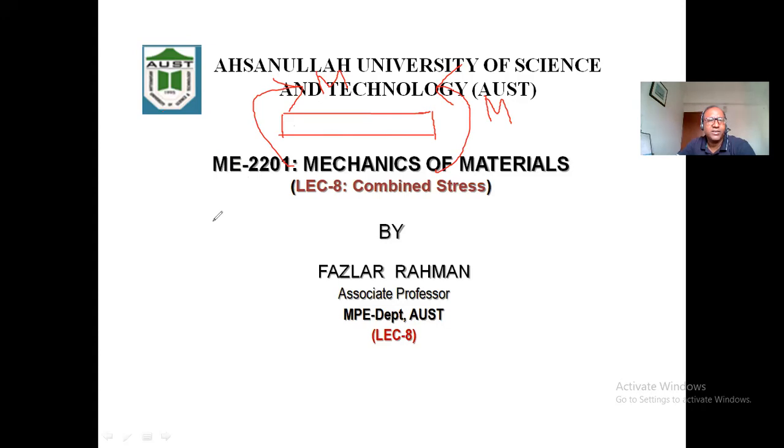I can think that this is one force working in the left direction, the other force working in the right direction. Say the depth of this beam is d. So this is also F, and this is d. So I can say that M equal to F into d.